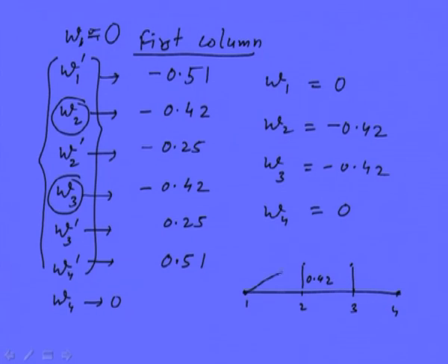If we join them by a quadratic or cubic curve, the shape function gives this kind of curve, which is nothing but a half sine wave, and we know that for a simply supported beam, the first mode is a half sine wave.